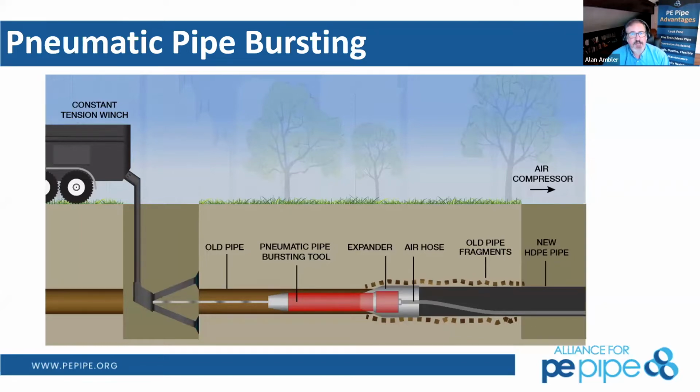And we are happy to put back something very stout and stable for your service connection, either an electrofusion fitting, mechanical fitting, some type of socket or fusion itself through that service connection, because that'll stop any inflow and infiltration for gravity sewer. That water does run along pipelines and some cured-in-place pipe liners as well, and finds a way in.